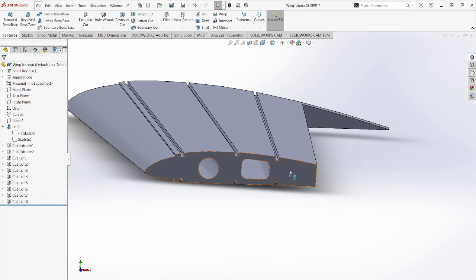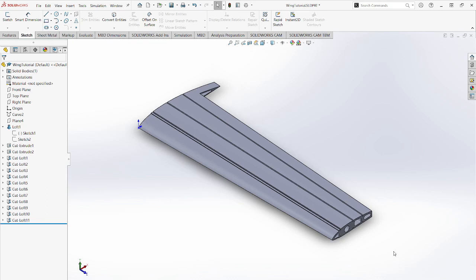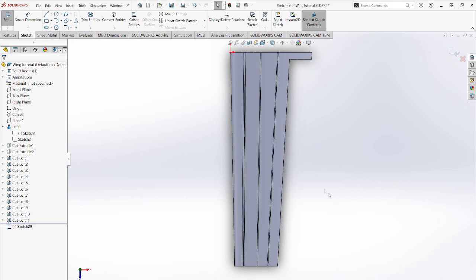We will do that for our other back section here, and then our front area here, as well as this area on this side. So once you have all of your optimization holes filled out, you are now ready to slice up the ribs. We're going to do this by making a sketch onto the top plane. And this sketch is going to be one big extruded cut through all, which will divide this up into little slices, which are going to be our ribs.